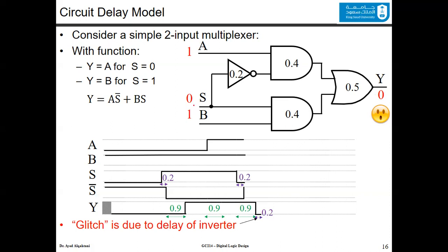Even if you were trying to figure out maybe it's B, maybe I made some mistake in the design, neither the value of A was passed to the output, nor even the value of B. So this is an unexpected behavior. This unexpected behavior was because of the delays in the circuit. This is why we need to worry about it and organize it in sequential circuit.